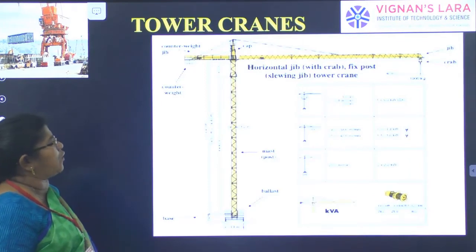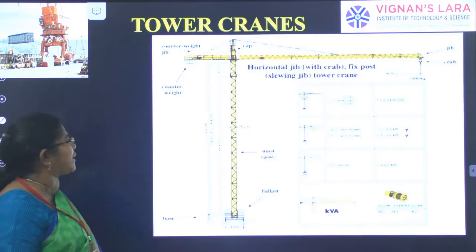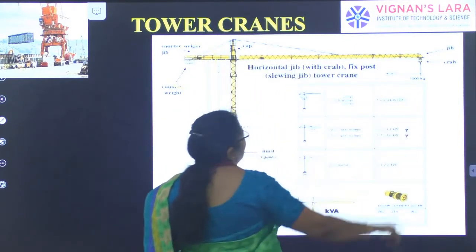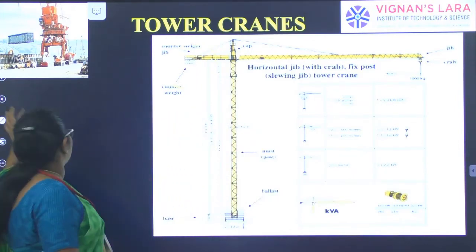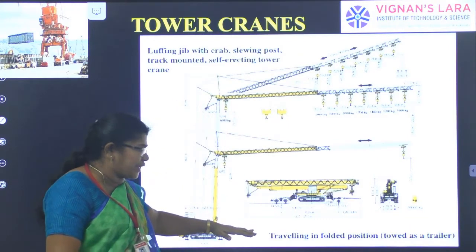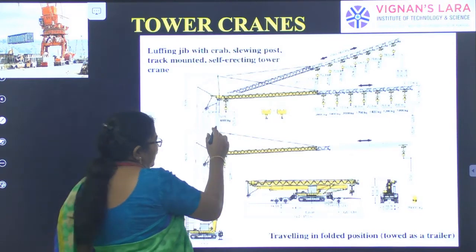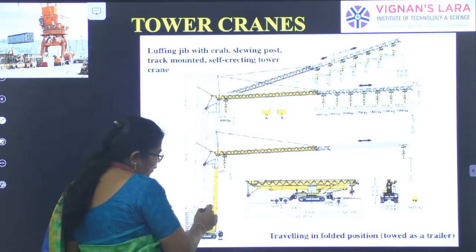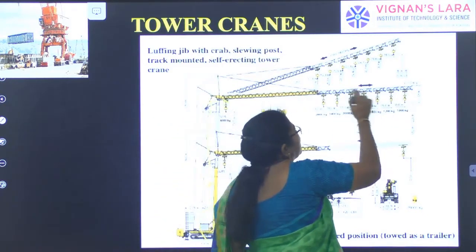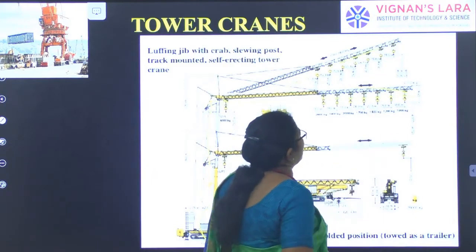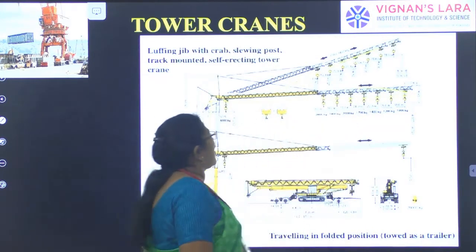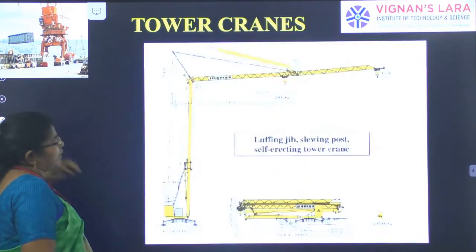So this is one of the other diagrams for the tower cranes. You can see this is the counterweight jib and winch. This is the rope that is connected with the hooks to take the loads. So you can see that even the jib, if we want to get it to a very low position, we can bring it down. With the help of the hydraulic load, we can adjust this distance, and this arm can be shifted like this. And also you can see here the weight that this arm can take is given based on the angles. Mostly 45 degrees up and down can be permitted.